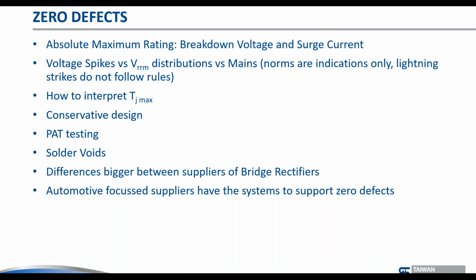For example, people want to save some money, and instead of a 0.8 millimeter wire, save some copper and ship 0.7 millimeter wires. These things happen. You reduce a bit of copper in a bridge rectifier, and those are all things that I've seen happen. So for these type of components, the older components, actual bridges and that type of stuff, you better know your supplier here.